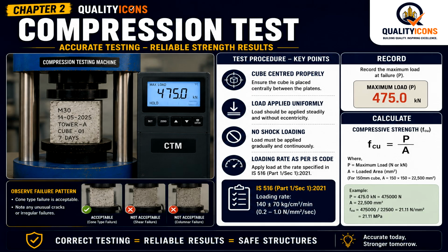During testing, the loading rate also is very important, guys. Apply load at the rate specified in IS 516. The loading rate is equal to 140 plus or minus 70 kg per square centimeter per minute.